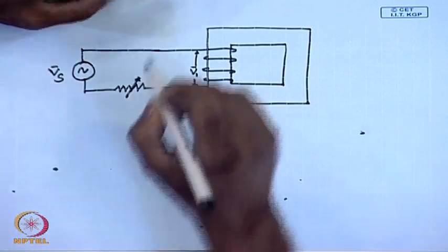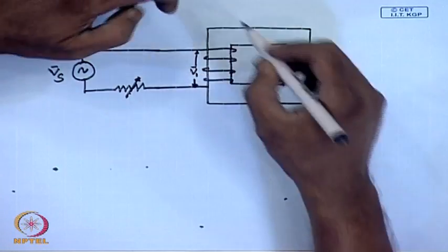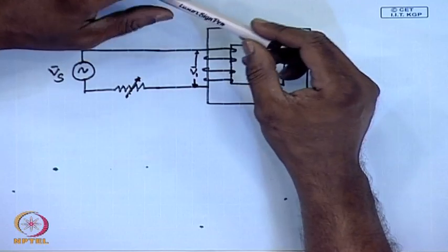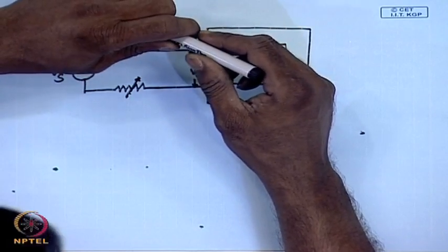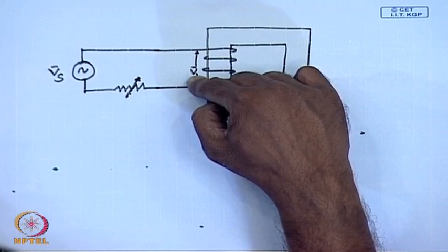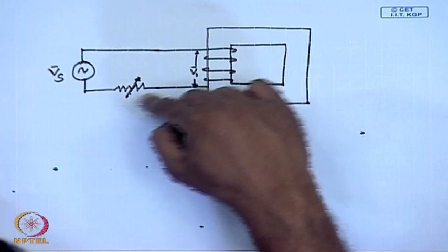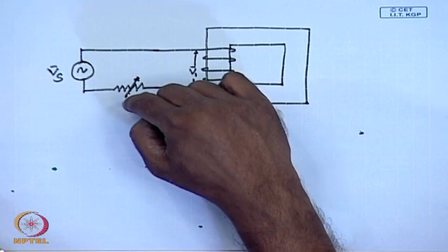However, this is not recommended, since if we add additional resistance, then there will be non-sinusoidal current flowing under no load condition through this transformer, which will make the applied voltage waveform also non-sinusoidal because of non-sinusoidal harmonic drop in the added resistance.